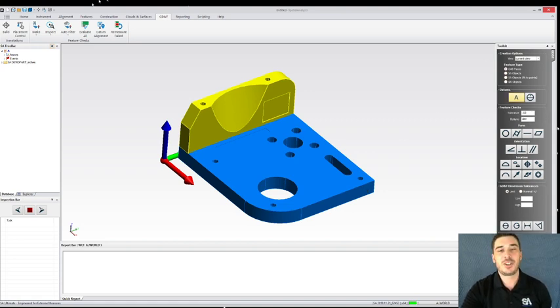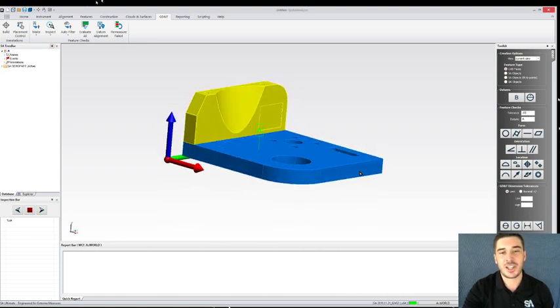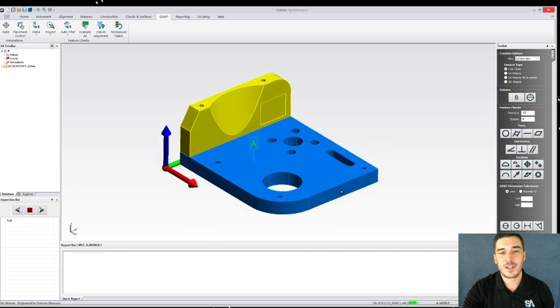So in order to create your GD&T, first of all, we'll start with datums, and we'll select our datums on our part. So I'm going to be picking CAD faces as my nominal feature type. And I'm going to pick the datum, just click on the button, and then just click on your CAD model where you want to represent that nominal datum. So I've selected the top surface here as datum A, and then I hit enter, and you can see I can get the annotation on there, and it shows up easy to see.